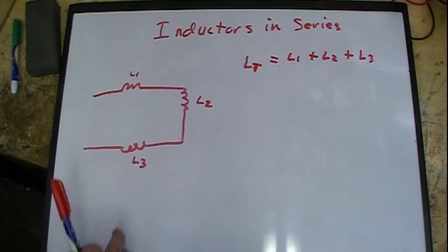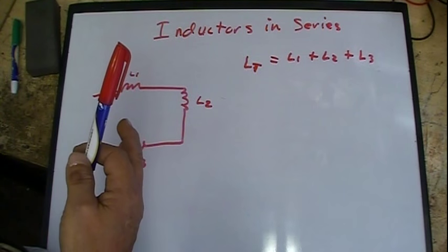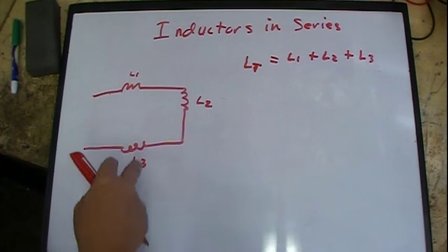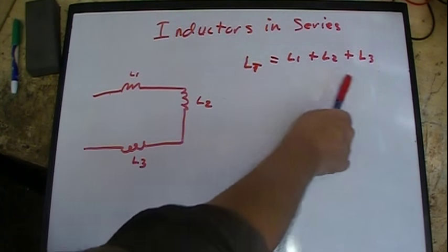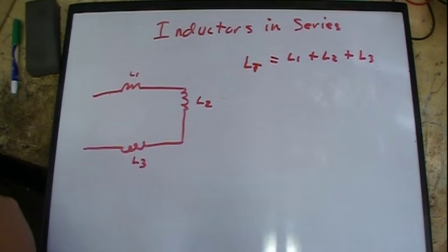In general, as long as these are separated so that they're not having any mutual inductance amongst them, that's all you use. It's just like series resistance, same formula.